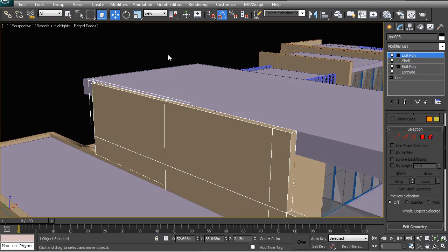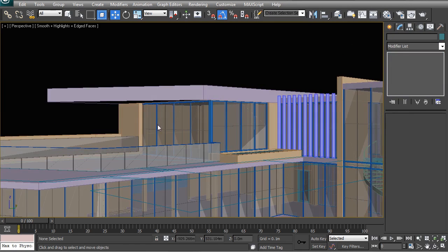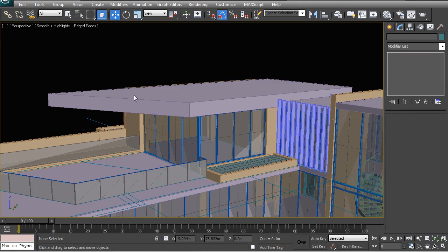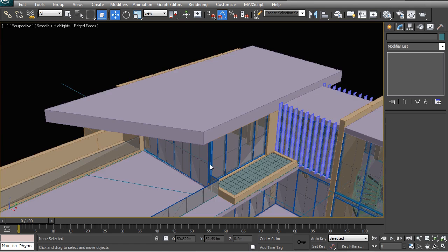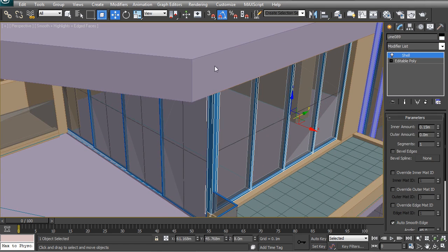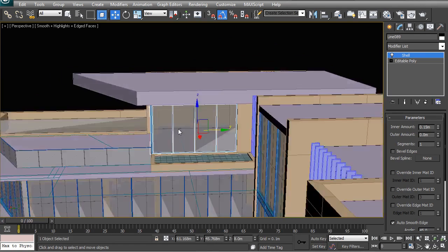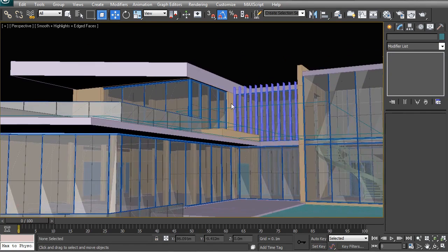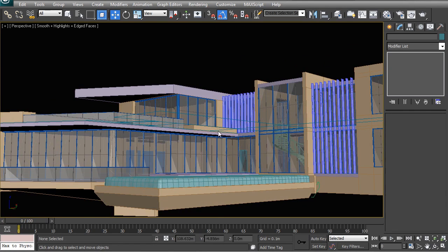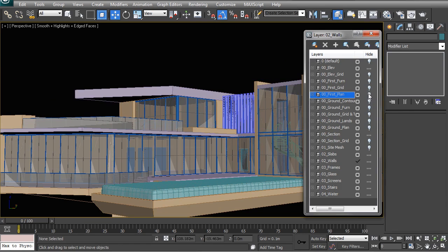So the result of everything that we've done is that we've pulled this roof up. We've made this ceiling a lot deeper, or at least the roof slab a lot deeper. Within it, there would most likely be a parapet. The whole thing wouldn't obviously be in solid concrete. It would just have the thickness acting as a beam, so it would have a concrete element or a steel element within it that would hold up this entire point. And also remember that part of the structure rests upon a very, very narrow steel column here. So tectonically, this is very difficult to do, but very often with architecture, these are the things that clients request, and then engineers scratch their head forever until they figure that all out.